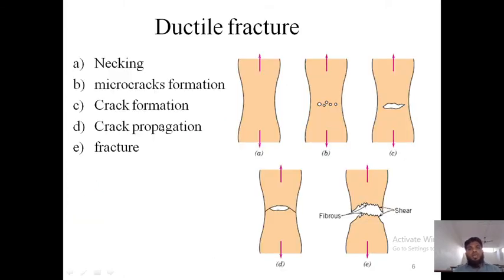Okay. So how necking is going to happen in plastic deformation is, when you are applying tensile stresses on a material, first of all its thickness will be reduced. For example, you take a rod and you are stretching the rod from two sides, the length of the rod will be increasing and the thickness of the rod will be decreasing. That thickness is nothing but the diameter of the rod, which will decrease, and that is shown by this curvature. So it will first decrease.